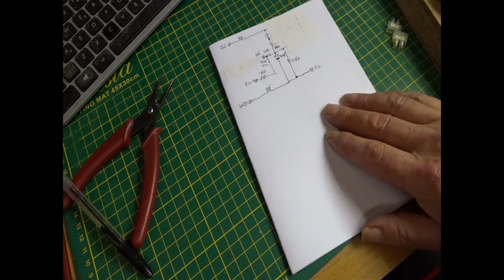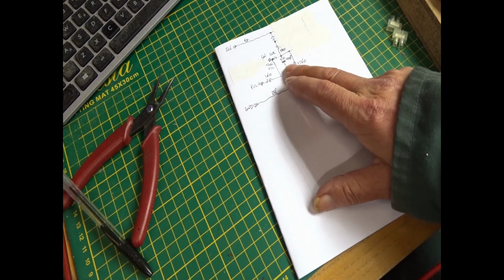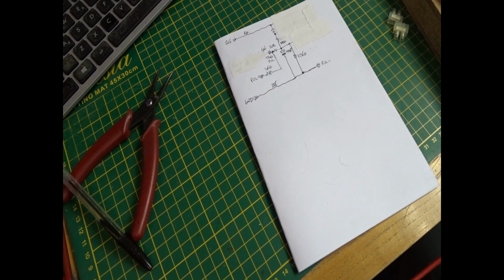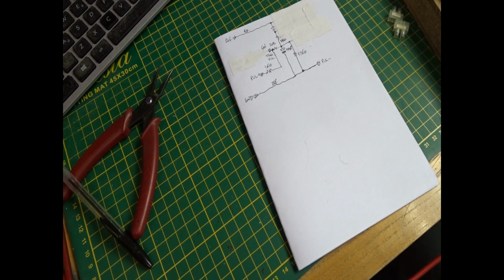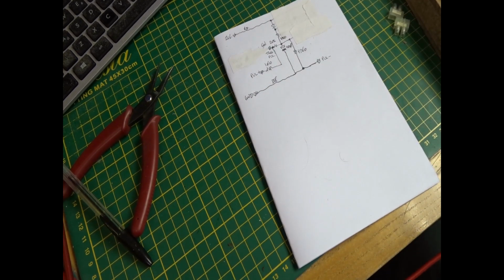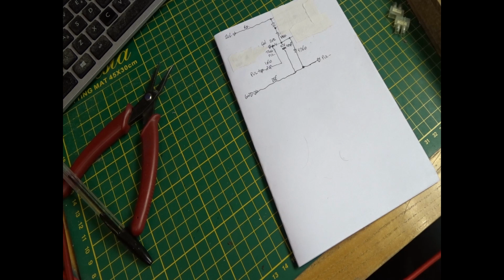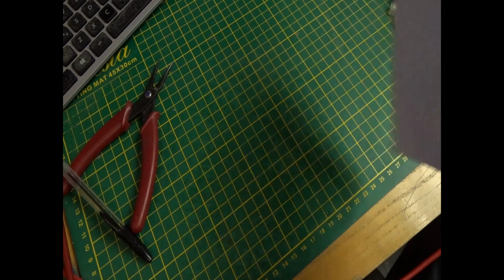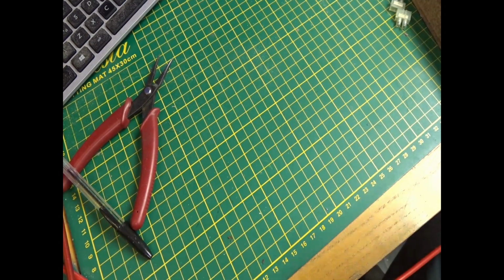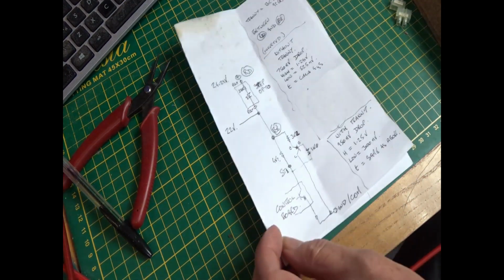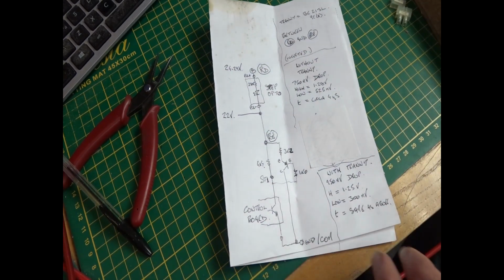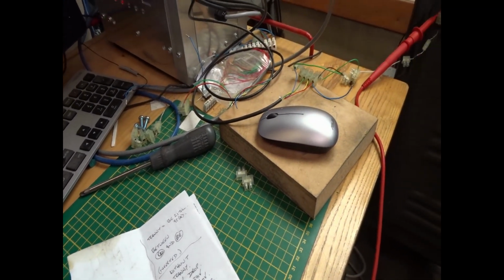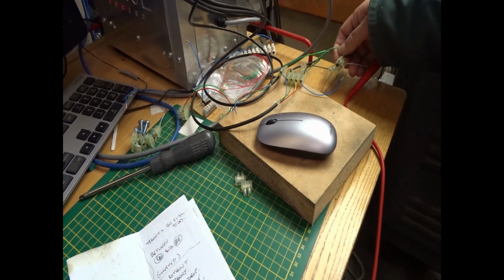And I tried this little circuit. I was using a cap to slow down the rise in the voltage after it falls from getting a low pulse. I was able to drag out the pulse length to about 6 microseconds. But again, scrapping it. Then I tried this circuit. I'm using a little transistor. I don't know if you can see it there. There it is there.